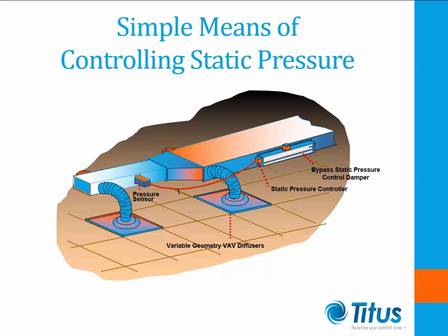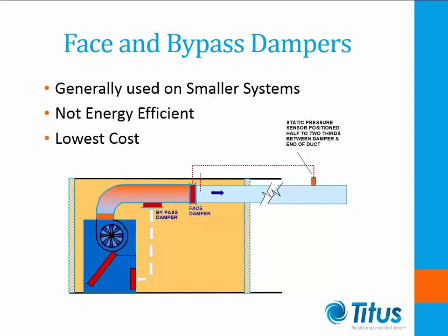This also is a less than ideal duct design because it uses high fan energy, and the conditioned air is not all being delivered to the space. An alternative to dumping treated air into the plenum would be to control the volume of air at the air handler by using dampers. This is generally low cost, but also lowers efficiency. To increase efficiency, the bypass should be ducted directly back to the return.